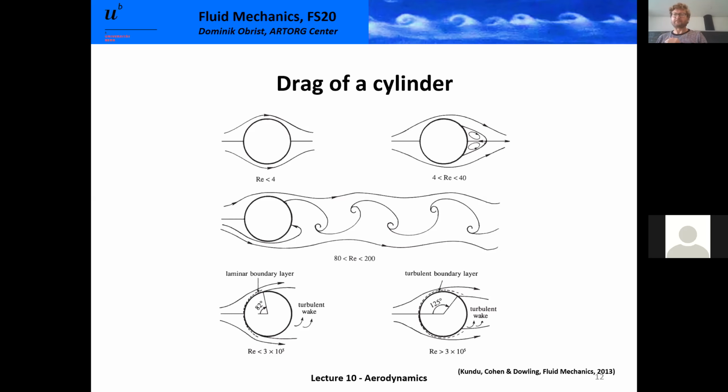So for flow separation, having turbulence is a good thing. And it's also good for the pressure drag. Because what happens to the wake? The wake has become much smaller. So instead of a huge wake on the left, where the flow separates at 82 degrees, we now have a much smaller wake. Okay, so by going over the critical Reynolds number of 300,000, we obtained a turbulent boundary layer,